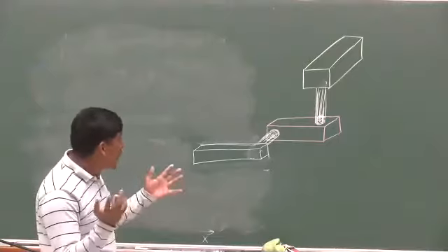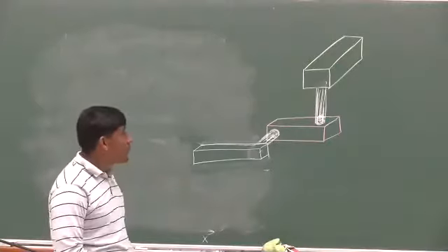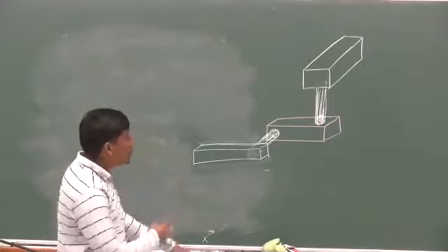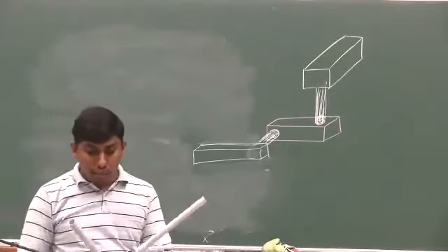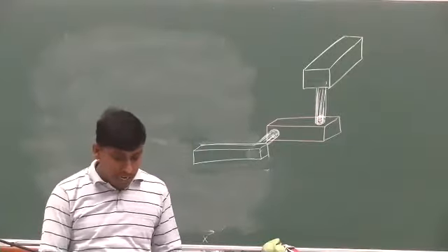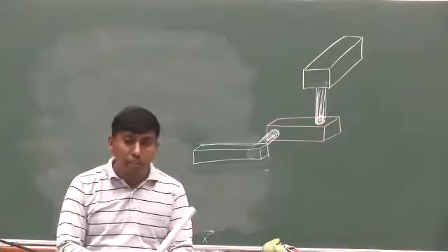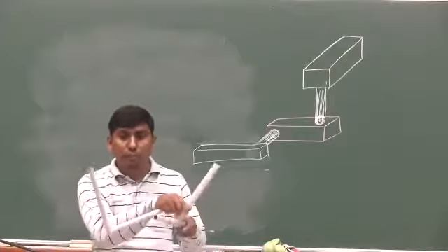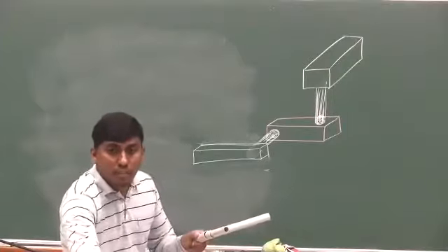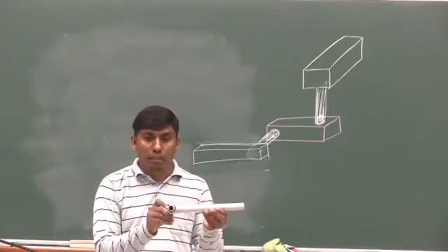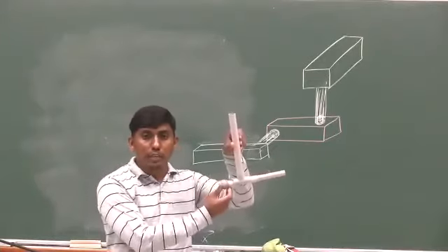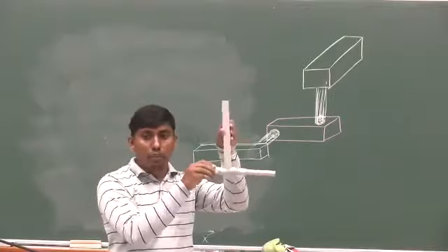So now I will explain the Denavit-Hartenberg parameters, that is, describe the Denavit-Hartenberg representation. For that, I'm taking this as the first body. This first body is rotatable with respect to this axis. So this is the first body and this is one joint.